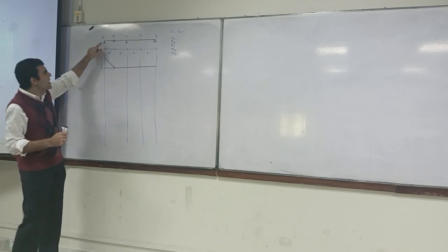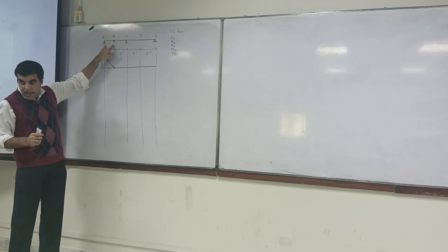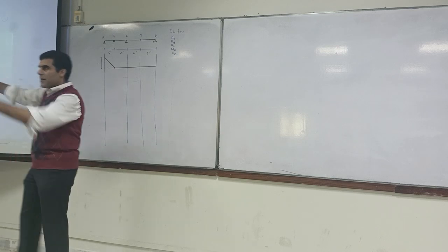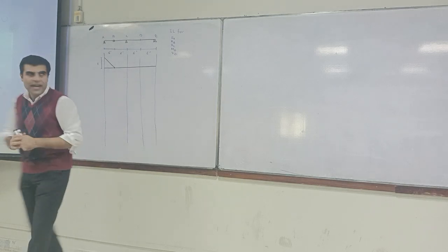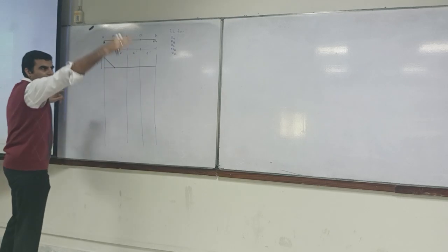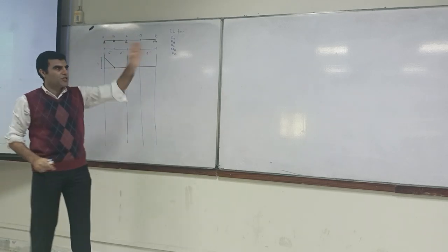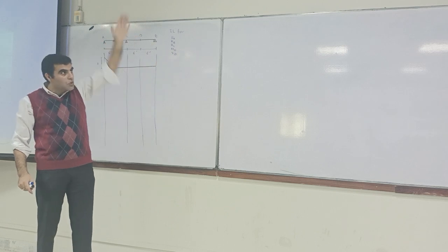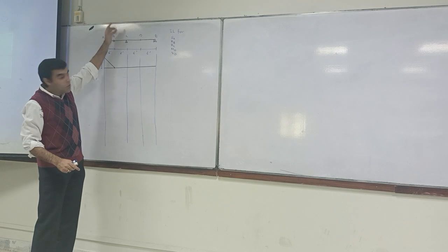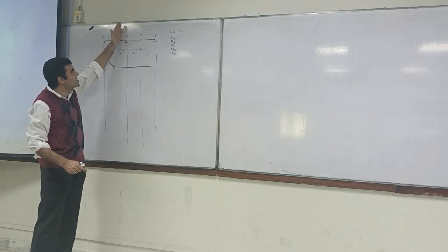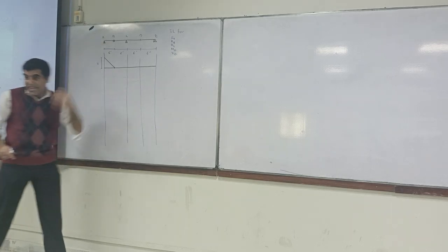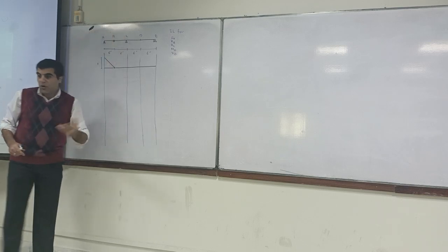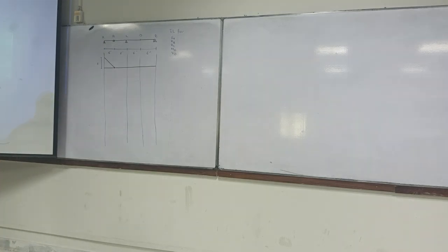If there is a facade over here, imagine this room, and in this room we have got a beam over here. This is our facade, and this beam is in this direction. We provide a pin over there, and there is a column load coming somewhere over here. We have got a choice either to place it over here or over there. But over here we have got the facade, so the facade will start taking the load, which we don't want. So we place it internally, so that the load doesn't get transferred. That sort of insight you also get from influence line diagrams.